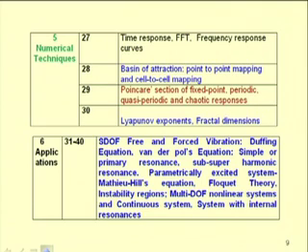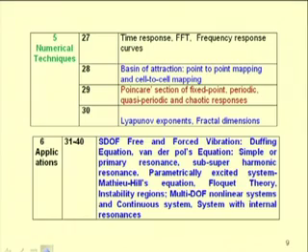The equations I already told you may be of the Duffing type, Van der Pol type equations, and in these cases we will see simple or primary resonances, subharmonic or superharmonic resonances. Then we may study the parametrically excited systems, which are of the Mathieu-Hill type of equation. There we will use the Floquet theory and we can study the instability region, and some cases of internal resonances also will be covered in this course.